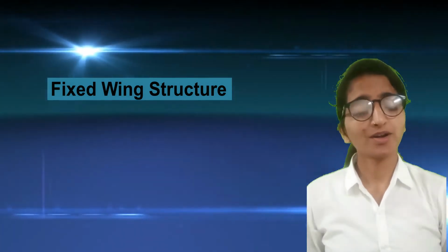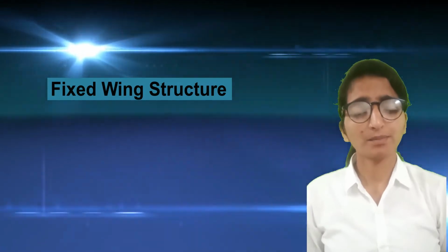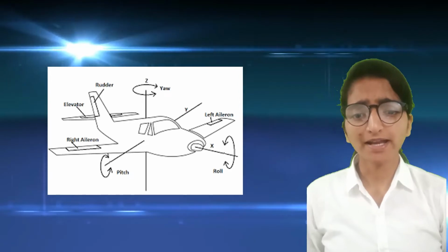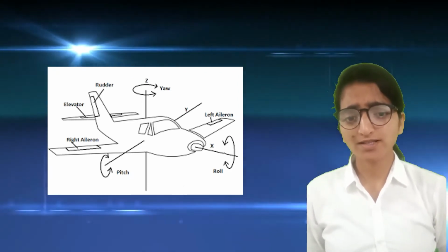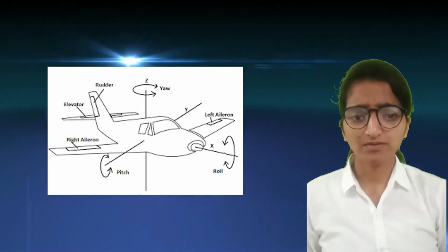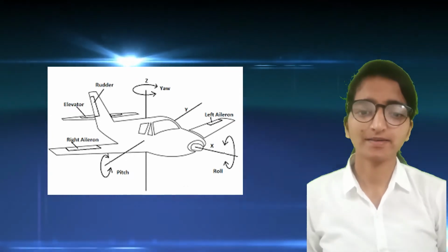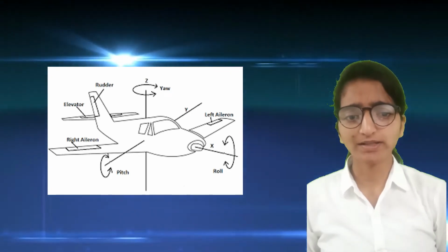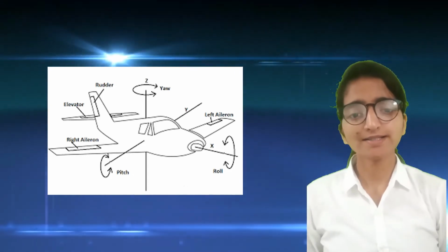Basically, all these components are explained in detail in lectures. The propeller is turned by an internal combustion engine or electric motor. Control of the UAVs comes from control surfaces built into the wing itself. These traditionally consist of aileron, elevator and rudder. They allow the UAVs to freely rotate around three axes that are perpendicular to each other and intersect at the UAV's center of gravity.